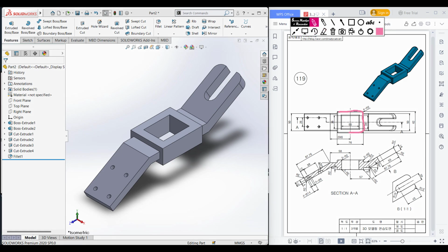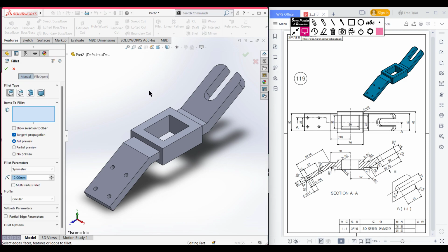Now press OK. Now isometric it, and now we can see in all the faces in our sketch, like here, here, and here. Okay, sorry, in here and also here. You can see that we have all the faces covered with fillet, and this fillet radius is 2 unit. So I will select 2 unit radius fillet and I will fillet all the faces. So I am selecting fillet option. Now select 2 unit. Now select this face.